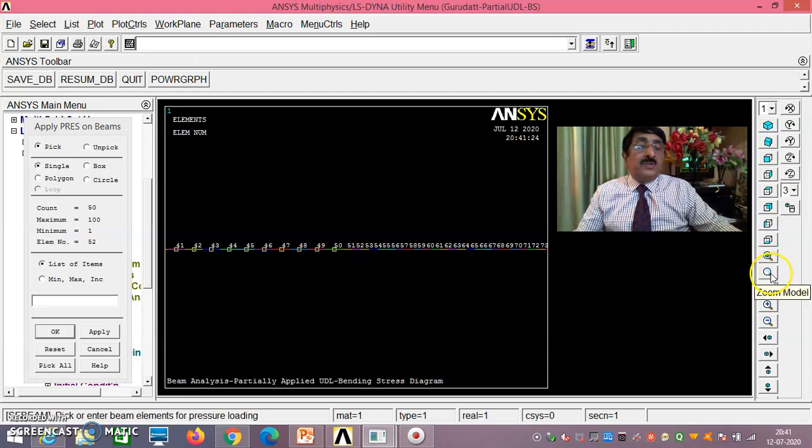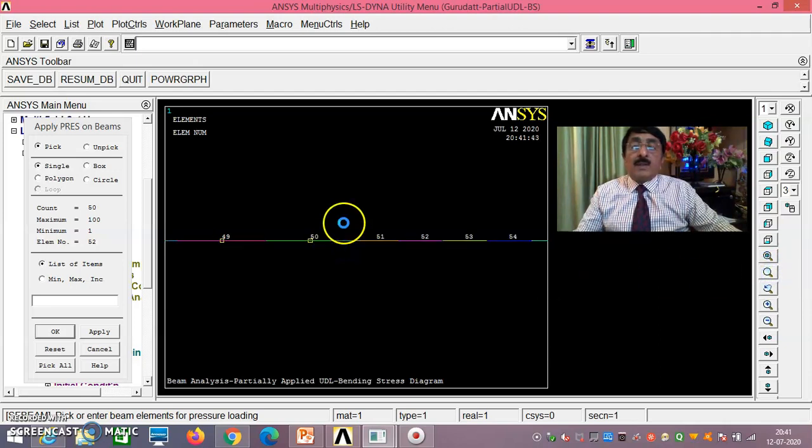As you see here, up to 50, 51 is this. You see 51, 52. These are all small ones. That's why you should immediately know that you should stop at 50 only. Be careful, you have to select only up to 50 elements. That is 4 meters only. 50, 51 and up to 100 is 2 meters only. It's all small length elements. Be careful about that.